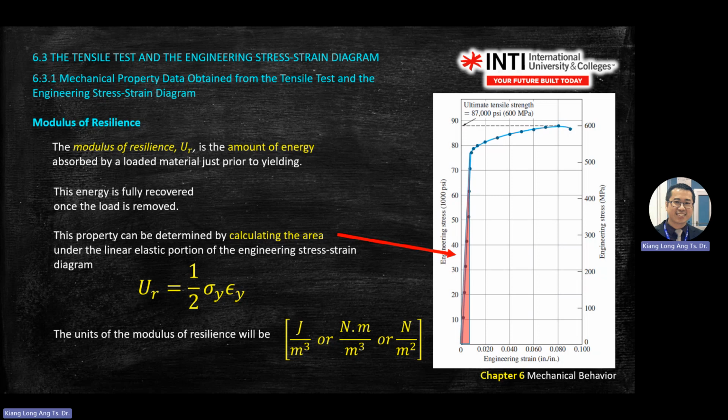When you are in tension, what happens to your lateral direction is shrinking, the middle part shrinks, the area shrinks, so the lateral will be a negative value. Negative times negative gives a positive value. Then the longitudinal is always positive. So in the tensile condition, you apply Poisson ratio equals negative strain lateral divided by strain longitudinal.